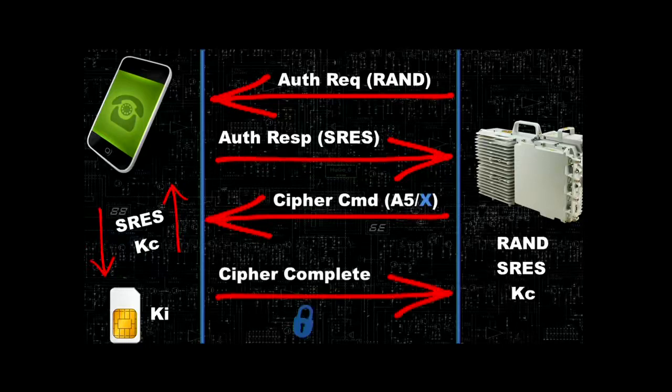Then it sends out a command to start encryption, using the Kc key. And as you can see from this algorithm, there's nothing that prevents the intruder from substituting the base station and bypassing the encryption. We have A5/1, A5/2 is not used, A5/3 is more reliable, but A5/1 can be cracked in a second using professional decryption devices.